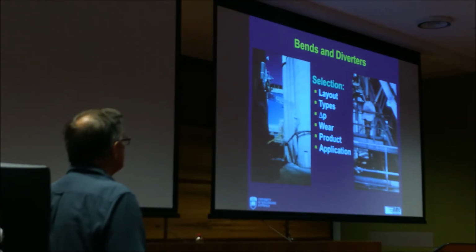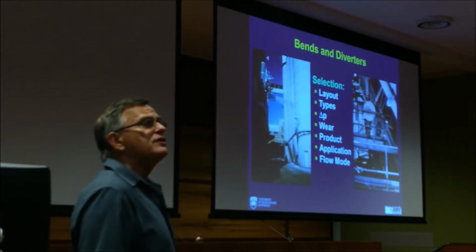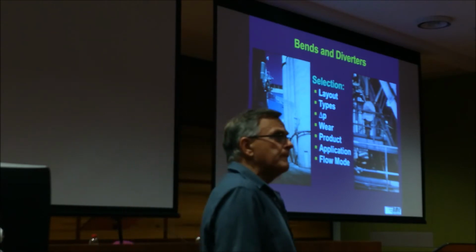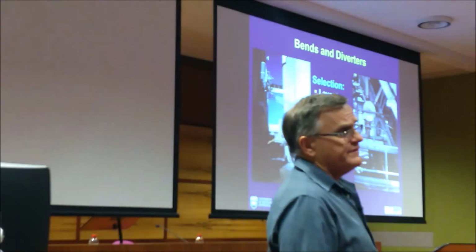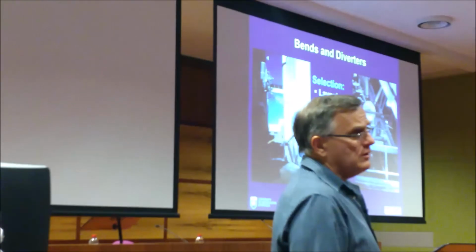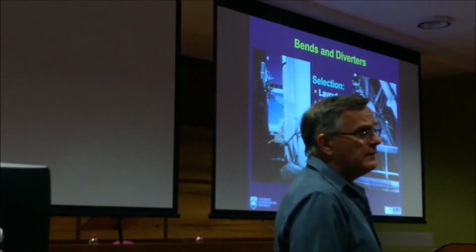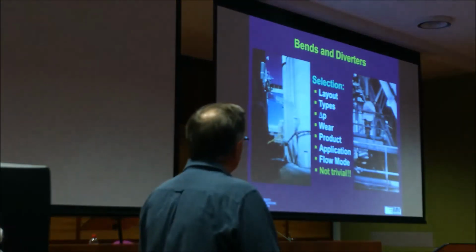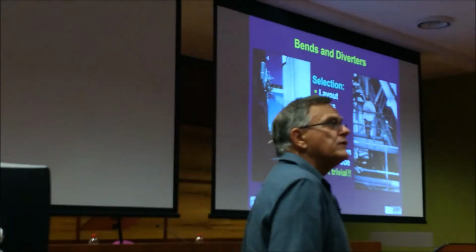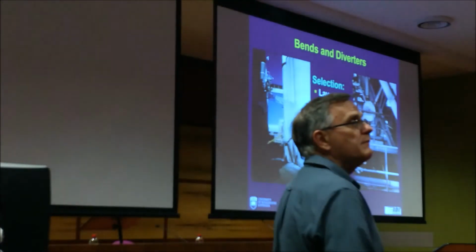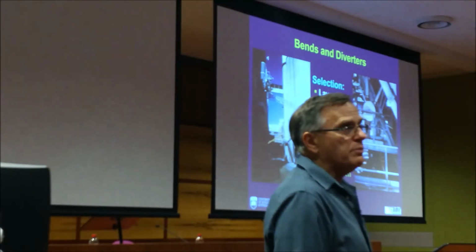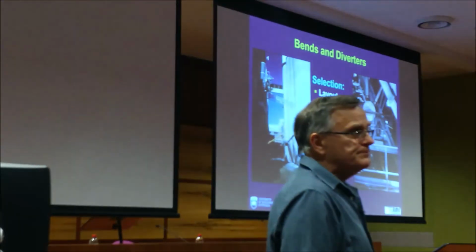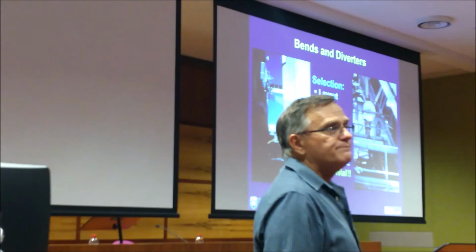So it's very application dependent, and also depends on how you convey your product, whether it's dilute phase or dense phase. That will also affect what components you need to pick. So it's definitely not a trivial task when you're selecting your bends and diverters. You need to put a fair bit of thought into it to make sure those components are matched properly to the product and the application. If not, your system will fail.